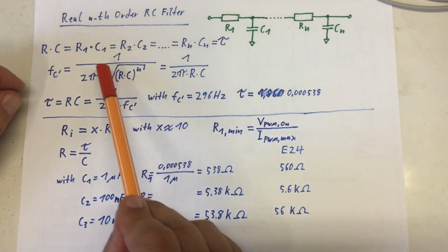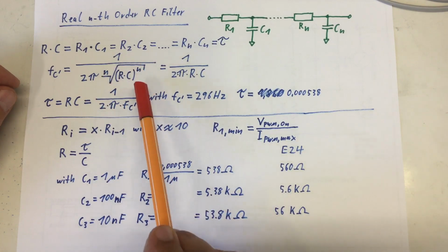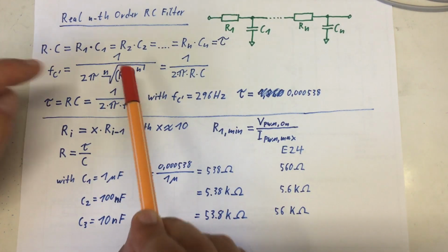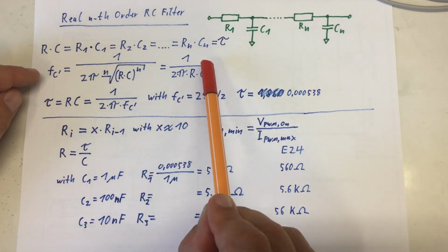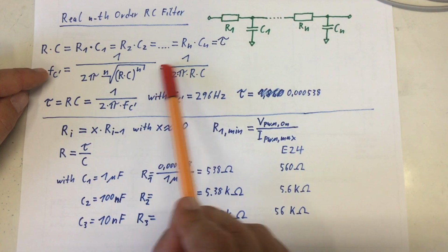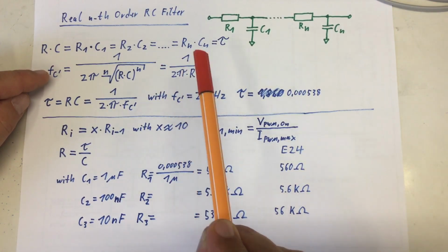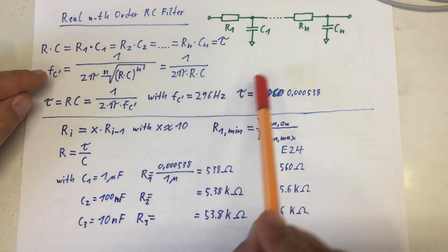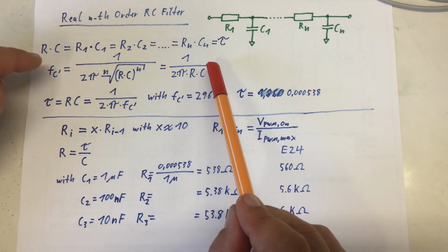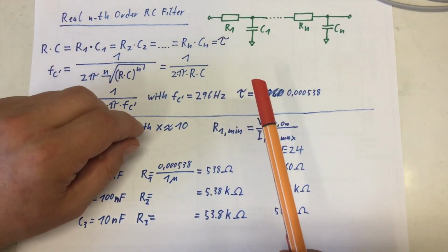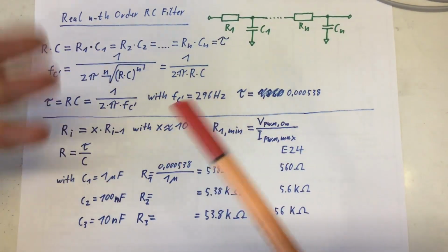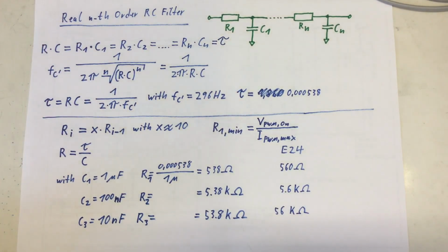And incidentally, the nth root of something to the power of n is the thing itself. So our general formula collapses to 1 over 2 pi RC. And there the circle closes. And we are back at the cutoff frequency for a first order filter, which simplifies things enormously.